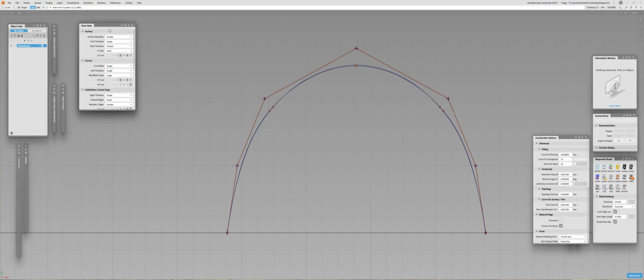an ability to create everything from smooth automotive surfaces to intricate freeform shapes. Understanding the core principles of NURBS, whether it's the predictable uniformity of edit points or the principle of trade-off between complexity and control with spans, equips you with the intuition to craft high quality designs while navigating the mathematical rabbit hole with relative confidence.